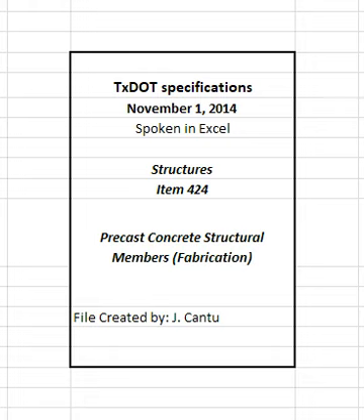4.2.5.3 Consolidation of concrete. Consolidate concrete thoroughly with high-frequency vibration immediately after placement. For prestressed concrete beams and piling, internal vibration is required and may be supplemented with external vibration. Provide at least one on-site standby vibrator of the type being used for emergency use. Perform concrete vibration using trained personnel and proper timing and spacing to ensure adequate consolidation.